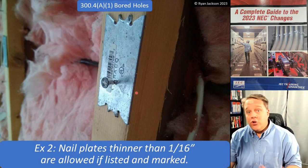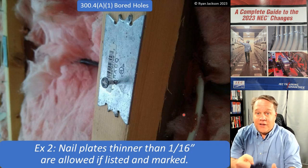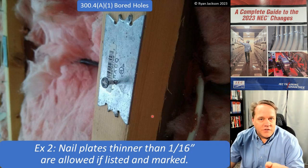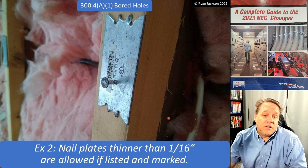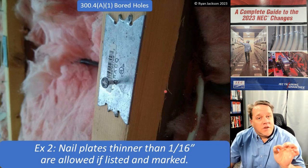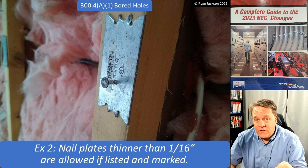But it should be hard enough that the drywall contractor realizes he's hitting a nail plate and he stops. So if you have thinner than 1/16 of an inch and it still passes the tests set forth in the product standard, then you can get it listed. The thinner ones are made out of case-hardened steel, and yeah, they're not 1/16 of an inch, but they're just as strong as typical steel that's 1/16 inch.